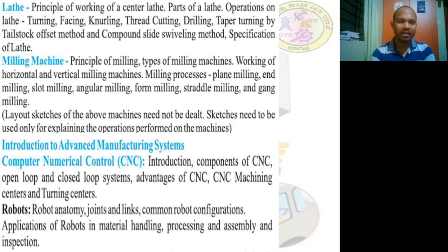It may be a turning operation. We will go in detail on what we mean by a turning operation. In the turning operation, a material's diameter will be reduced. For example, if this is a 12 dia, it will be reduced to 10 dia. And then we will also have a facing operation. In the facing operation, as the name itself indicates, the overall length will be reduced. The length of the workpiece will be reduced in the facing operation.